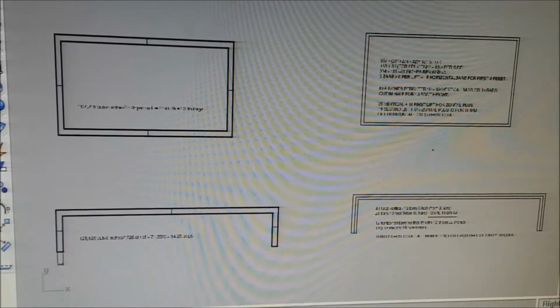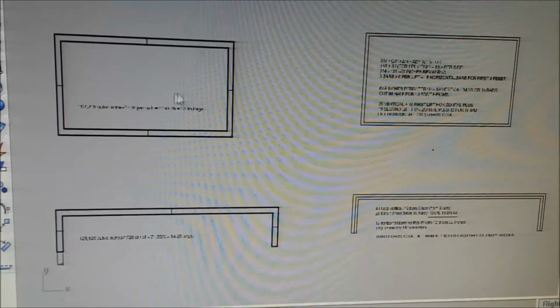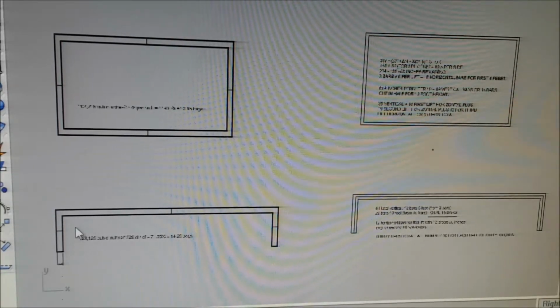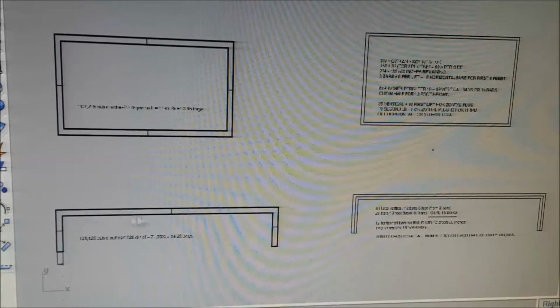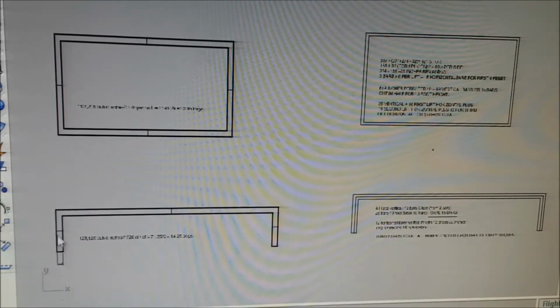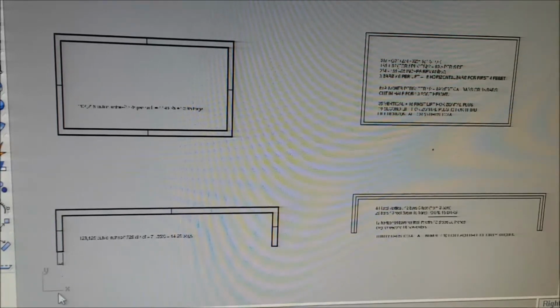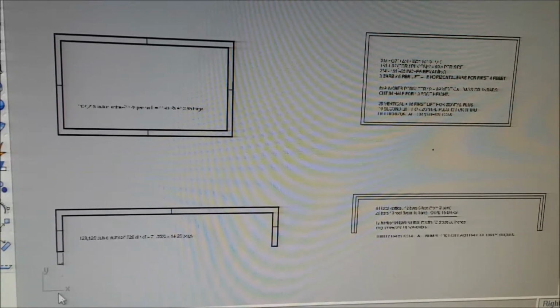The two examples we're going to use are the outside perimeter of the septic tank, and this is one half of the dirty kitchen. There's a door off of both ends of the dirty kitchen, so it's a good separation point to slip form pour the wall over here so I can get my counter done. And then on the other side we're going to put another counter because we already have forms. We use those forms 7 times is the plan so far.